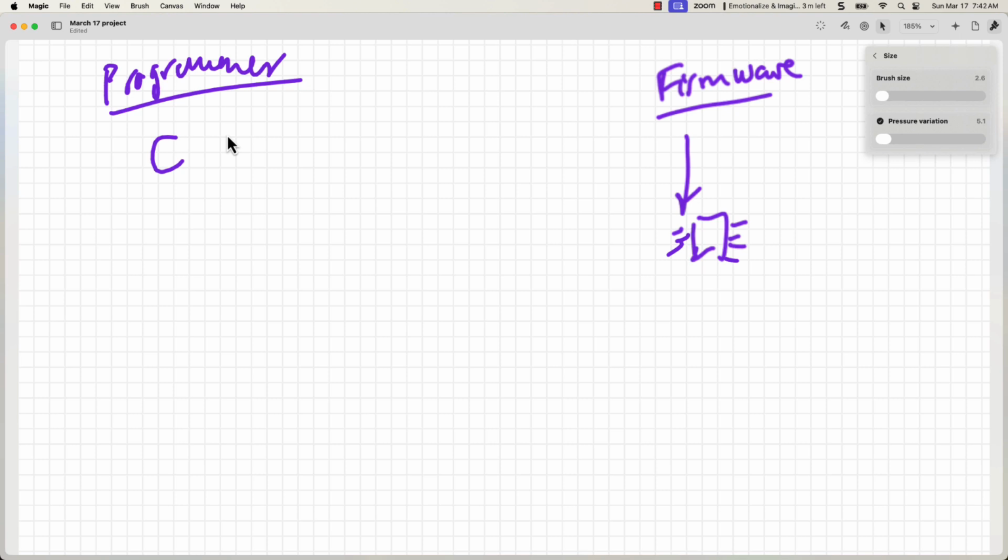That's your I2C bus. That's your PAM signals and everything. That's your RGMII signals and all these things. Your I3C, USB. That wiring, those protocols that are used, that's akin to our brain, our CPU, being connected to our arm or being connected to our spinal cord a specific way. It needs to use a certain protocol to communicate with different parts of the body. Okay, that's all set by the firmware engineer. Say, hey, make sure you talk to this one, that one. Now, as far as overall commands, we're not commanding anything yet. This is our lower level operating system.